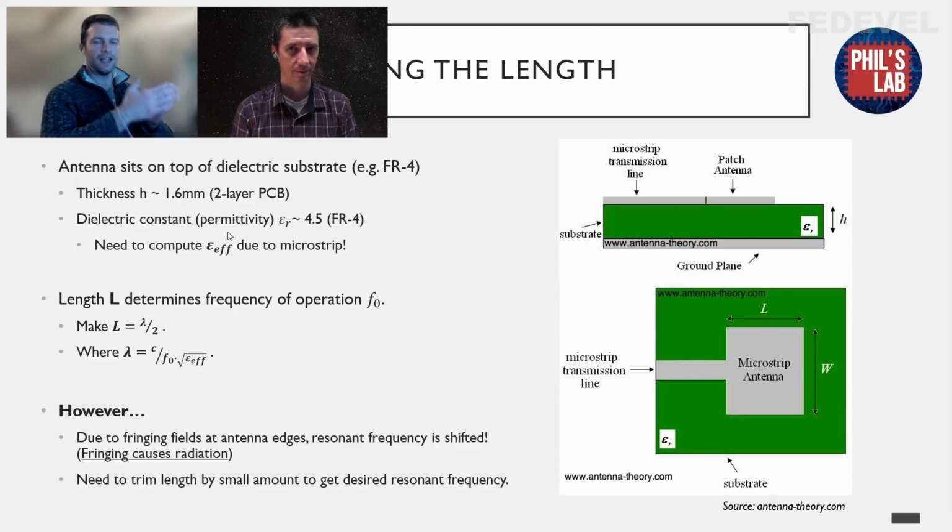We'll have several times where we'll need to calculate a different effective permittivity. One is for the antenna because it is so wide. Then we'll have some sort of feeding network we'll have to recalculate. And then we have the microstrip, the 50 ohm line we'll use, and we'll have to recalculate it for that as well. So it turns out we have to do this calculation quite a bit. But luckily there are calculators online, or the Saturn PCB Design Toolkit, that do it. But this is, I guess, fairly standard procedure for microstrip transmission lines.